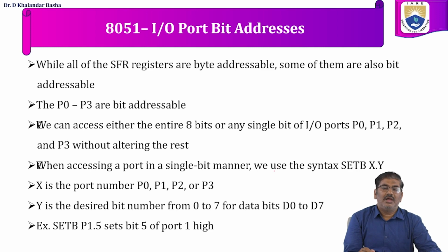Well, all the SFRs, which are registers, are byte addressable, as well as a few of the SFRs are bit addressable also. The ports, that is from port 0 to port 3, are byte addressable as well as bit addressable.